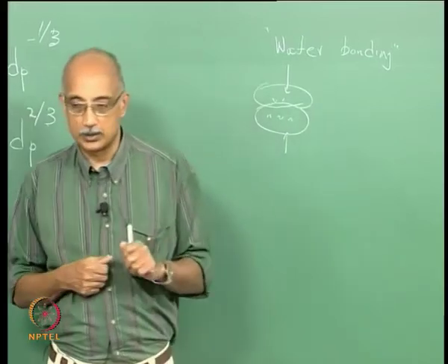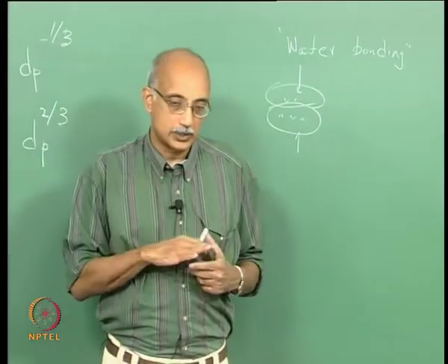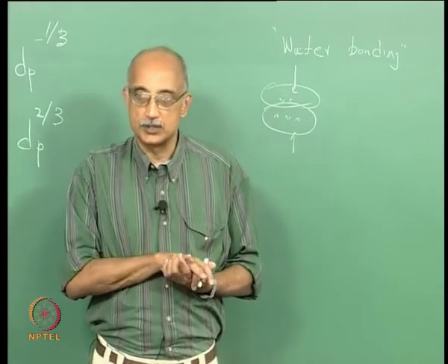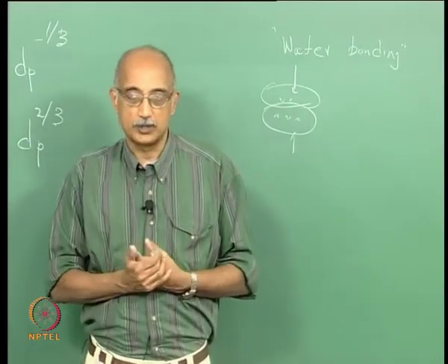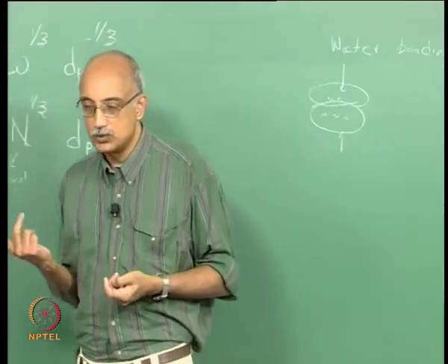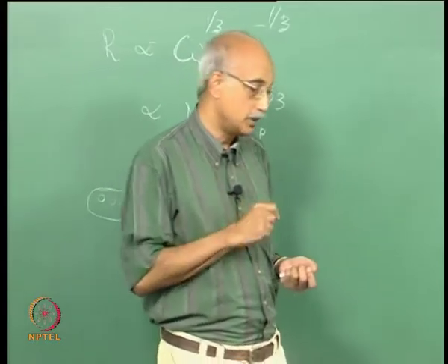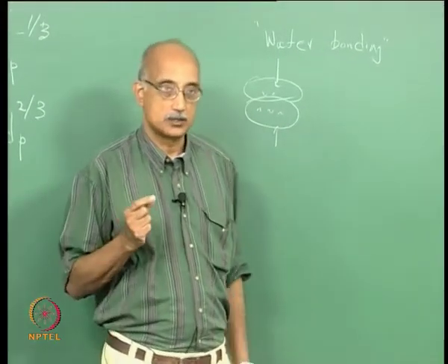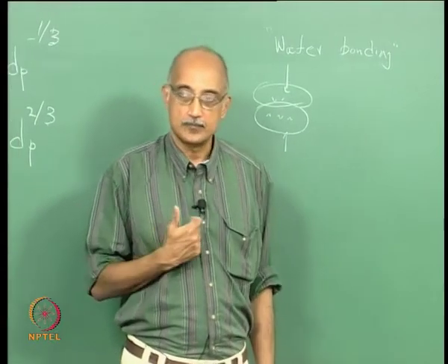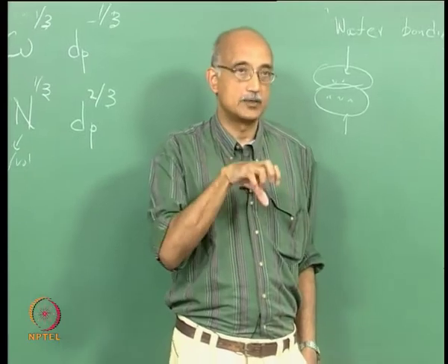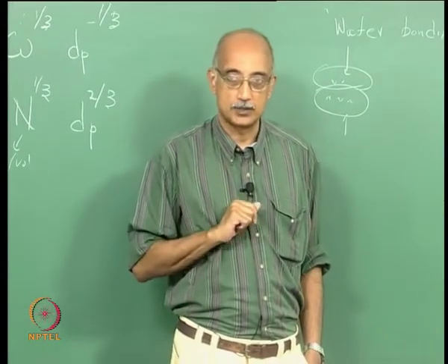is also important, and that again has to do with some of the characteristics we discussed earlier about particle adhesion to surfaces and particle removability from surfaces. And as we have discussed earlier, the two cleaning methods that are particularly suitable for submicron and nano sized particles are ultrasonic cleaning and megasonic cleaning, which are very effective in removing particles that are embedded in the surface as well as loose on the surface.